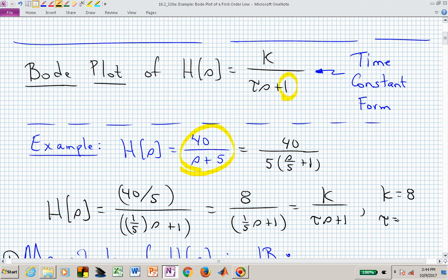And our time constant tau is 1/5 of a second, or 0.2 seconds, which in this case, after 5 of those time constants, or 5 times 0.2, I shouldn't have maybe picked 5 for my pole location, but now we have a settling time of 1 second.